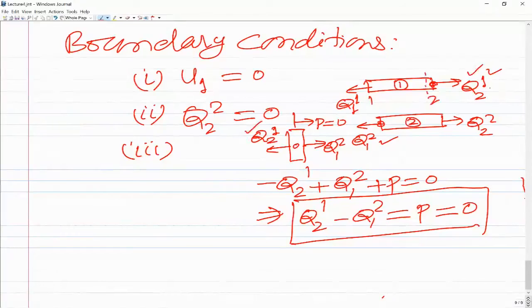Q21 is the force on the element at node 2. So on the node, when I draw the free body diagram of the node, this force is in the opposite direction. Similarly, this Q12 is the force on element 2's first node. When I draw the free body diagram of node 2, its opposite is going to act on this particular node 2, global node number 2. So that is how I have shown this, and what is shown is correct. These are the forces acting on the node, whereas these are the forces acting on the element, so they are shown in opposite directions. Thank you, sir.